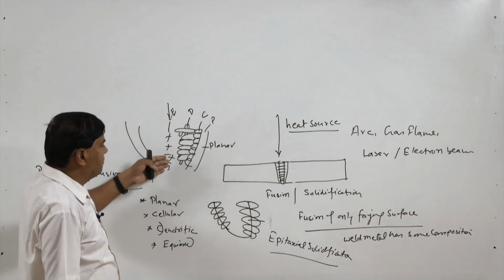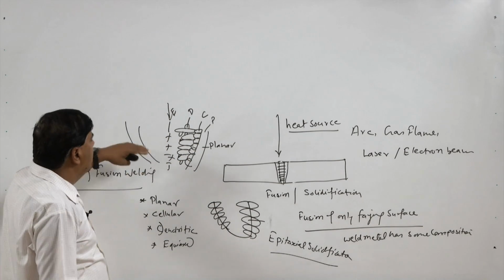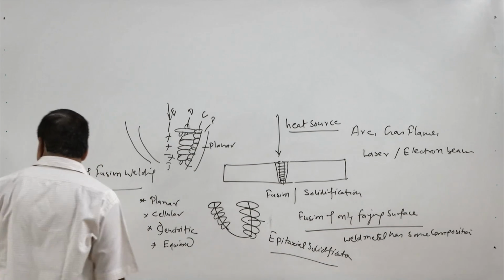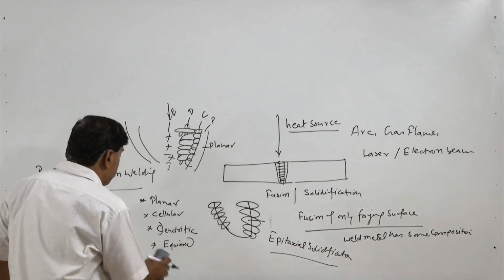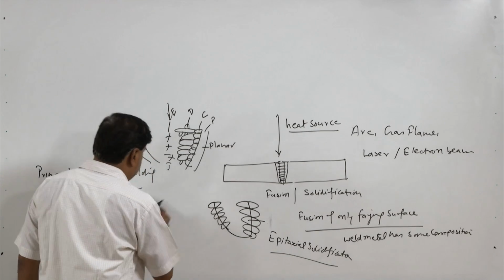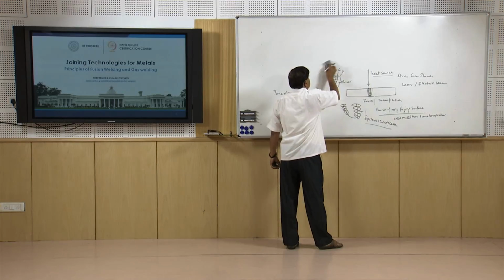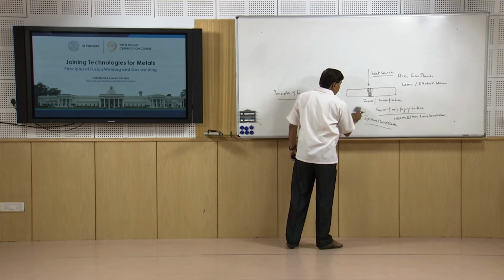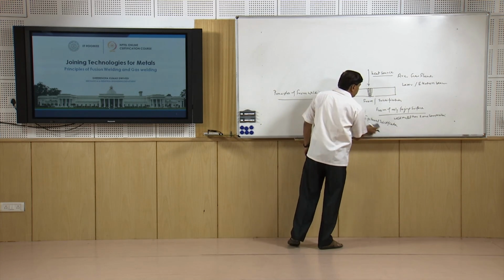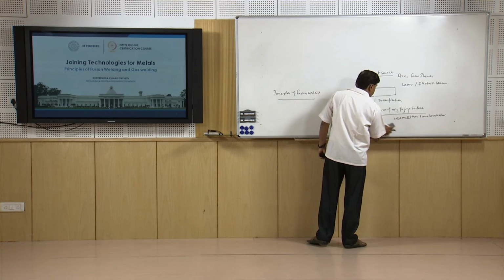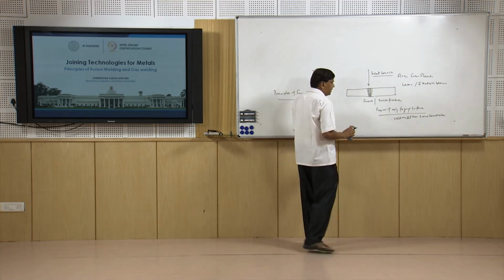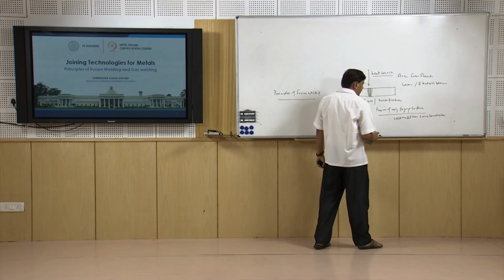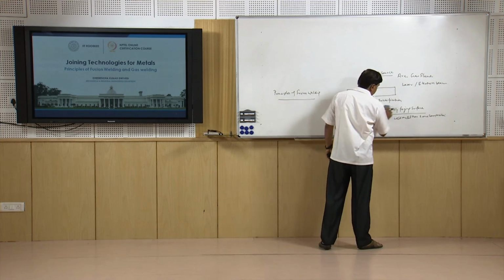It is always preferred to have the equiaxed grain structure, and therefore, to achieve this equiaxed grain structure, compositional modifications are carried out. But if the weld metal composition is different from the base metal, then first nucleation on the fusion boundary takes place, thereafter the growth occurs. So, that is typical nucleation, and the growth modes are involved, steps are involved for completion of the solidification.